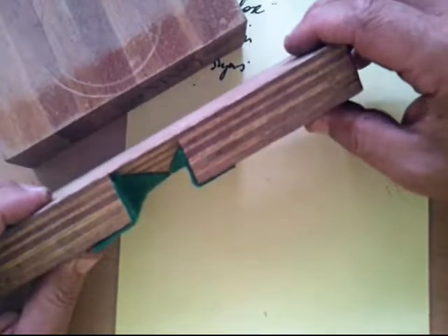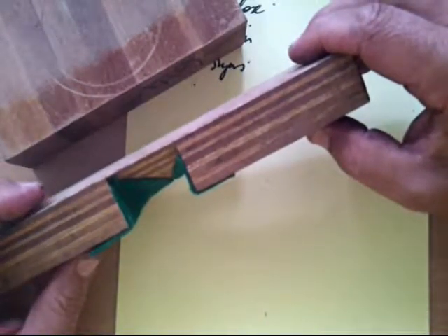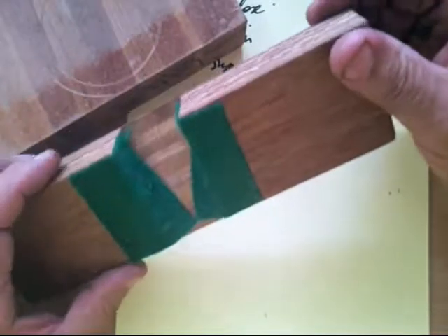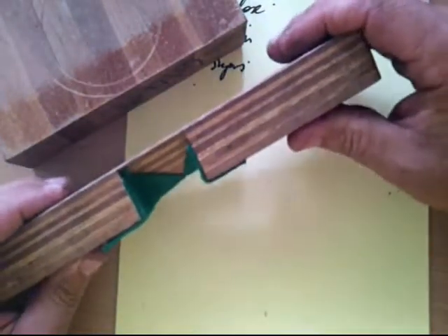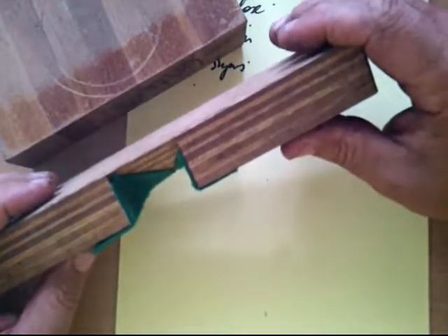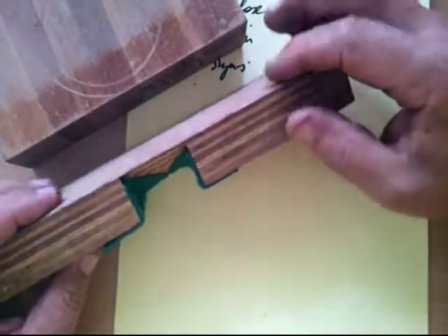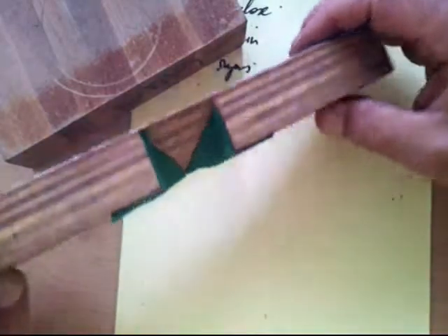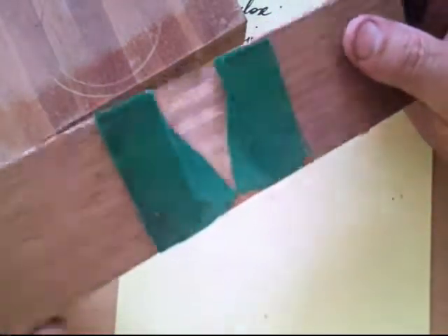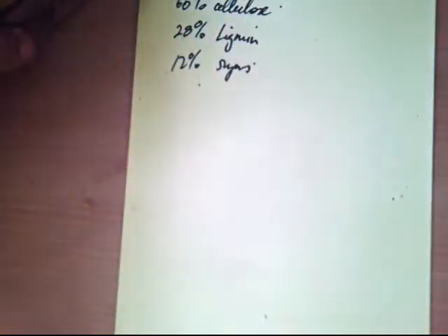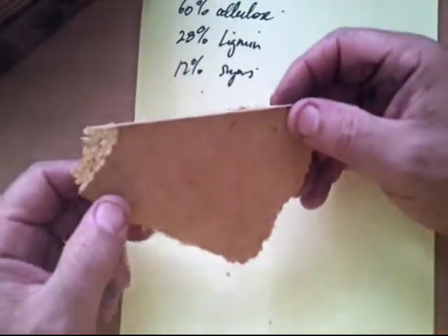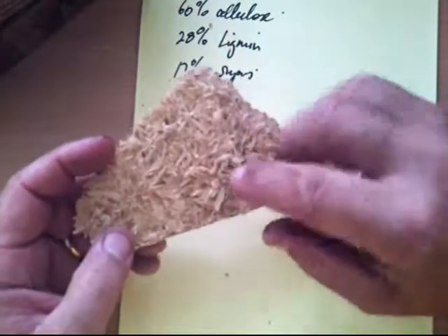Again, it has to be glued together, and you can see the striations indicate the grain direction. The darker ones being end grain, the lighter ones being along the grain of the different plies that have been put together. Okay, it's also used for formwork for concrete because of the strength properties, because of its lightness and ease of workability, and its renewable nature. It's used for bracing in houses, it's used for panelling, plywood is.